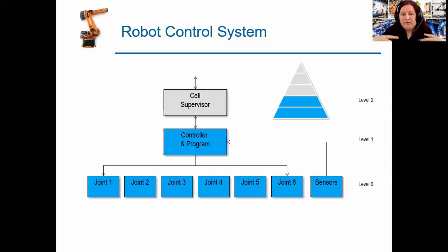And you have to make sure that, for example, if we have 6 degrees of freedom, we will have these 6 joints that we will have to control at every single time. And the controller of the robot has to talk to every single device, every one of these 6 different actuators, if it's electrical, hydraulic, or pneumatic.